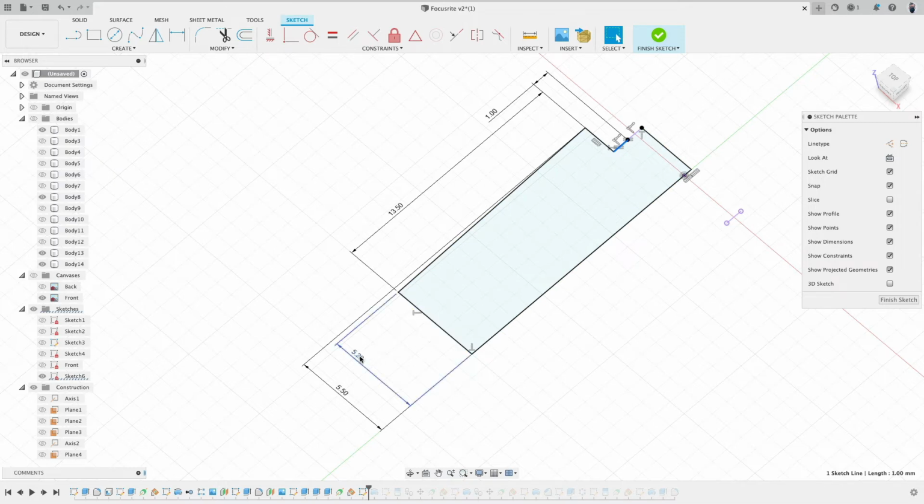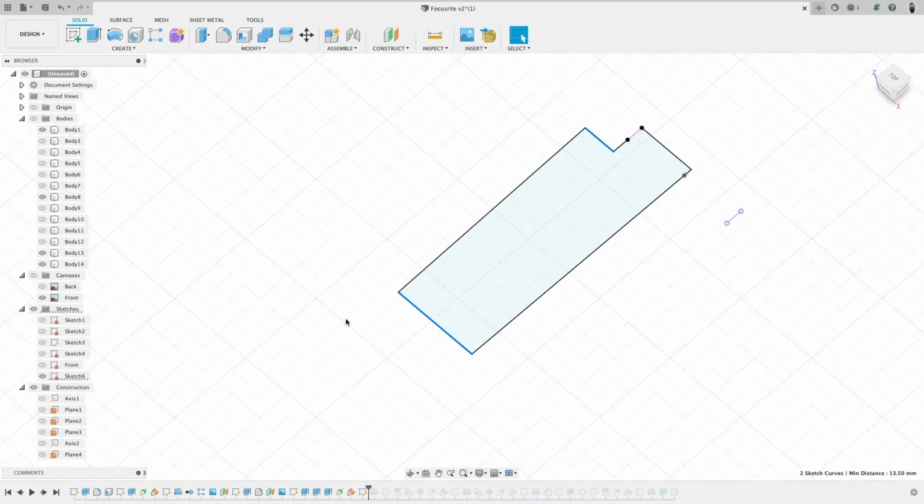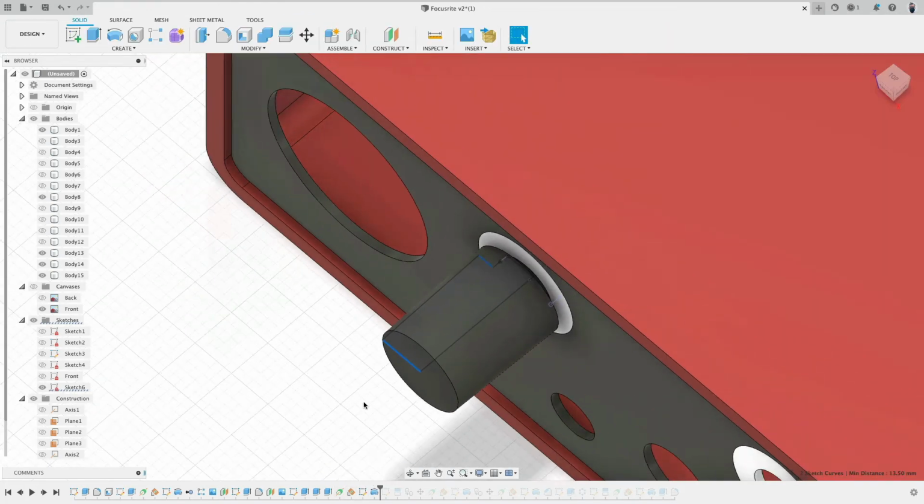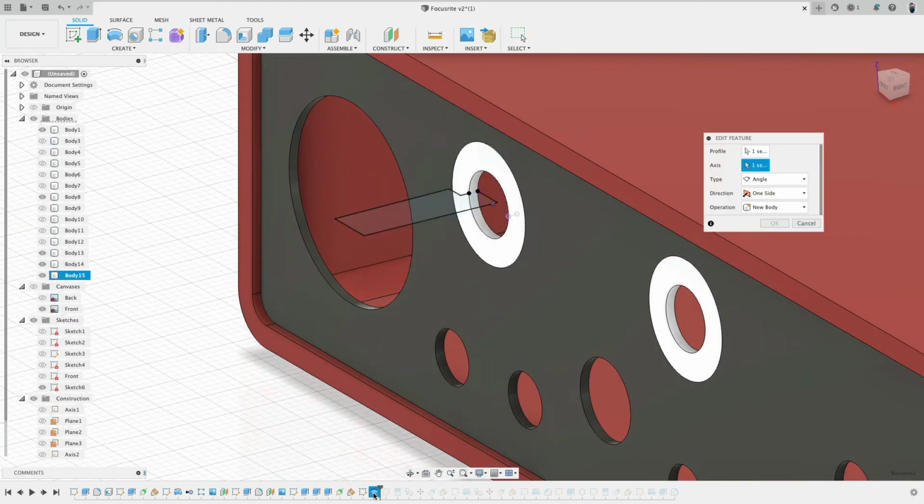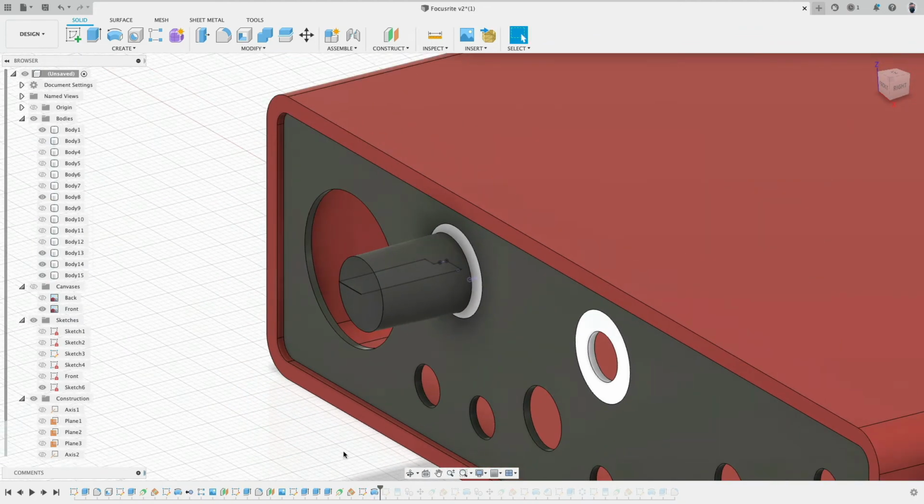The end is 5.2 millimeters. Actually, I measured the diameter and then I divided by 2. That gives me then the radius. And because it slightly tapers also from here, so from this point to this line, there is a readout of 11 millimeters divided by 2. And then this point to here, and that is 13.5. Okay, super easy. And then we do a revolve of that object. Also here again, new body, very good.